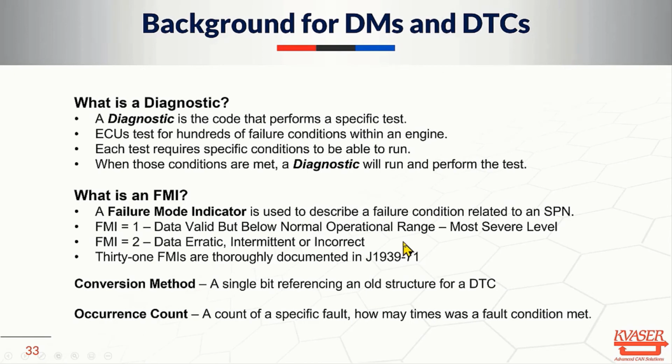The first thing we're going to understand is, what is a diagnostic? A diagnostic is code that runs to perform a specific test within the vehicle. So an ECU tests for hundreds of different failure conditions. Each test requires the engine to be in a pretty specific condition to run and test for some parameter. When those conditions are met, a diagnostic will run and will perform the test.